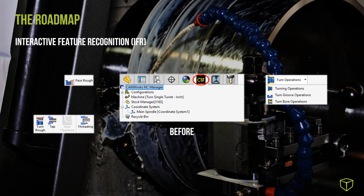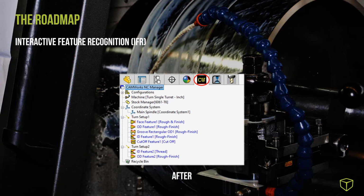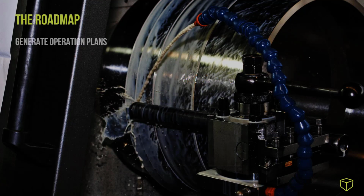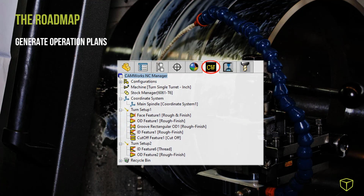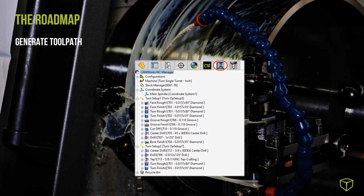And once all machinable features have been identified, generate that information into operation plans. This contains how each machinable feature is to be used and how the NC code will output. And from these operation plans, generate toolpath to see how each cutting tool is used for that specific operation.